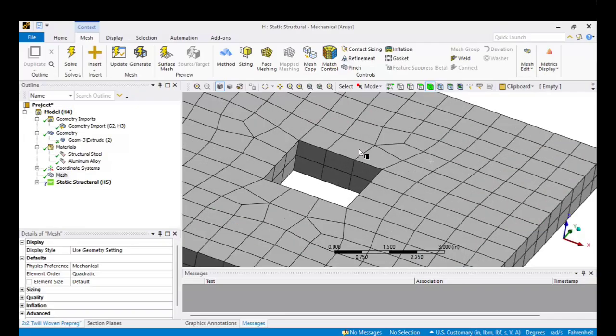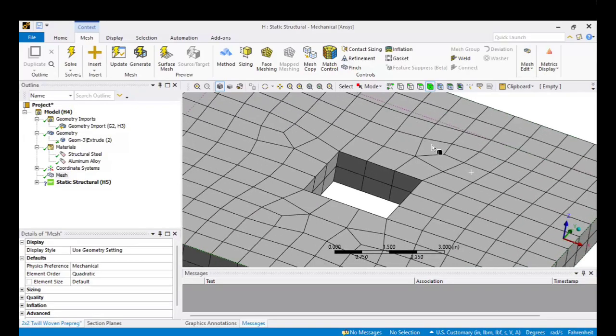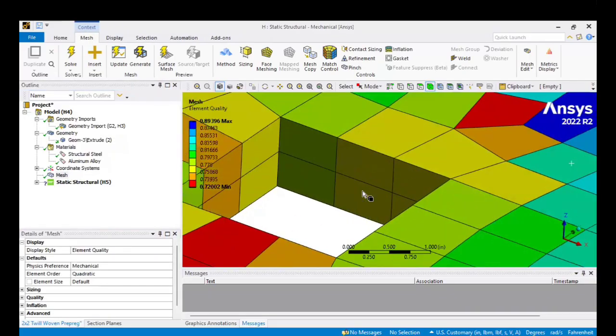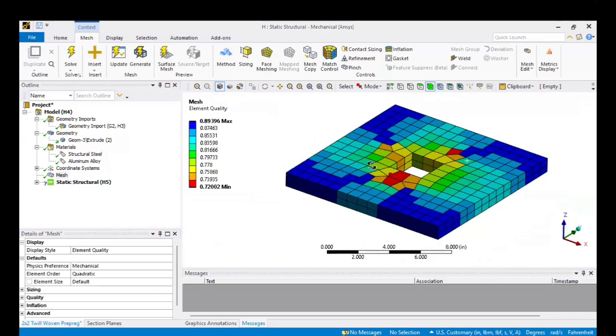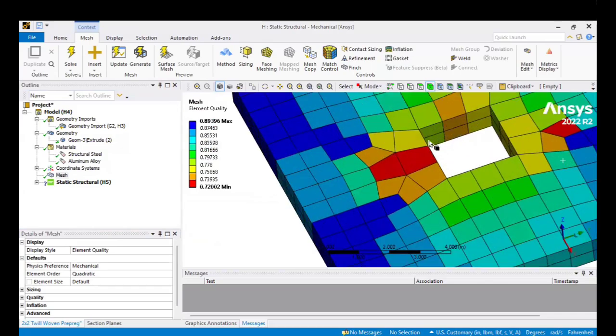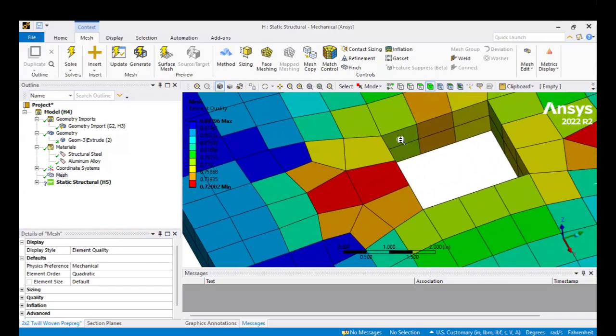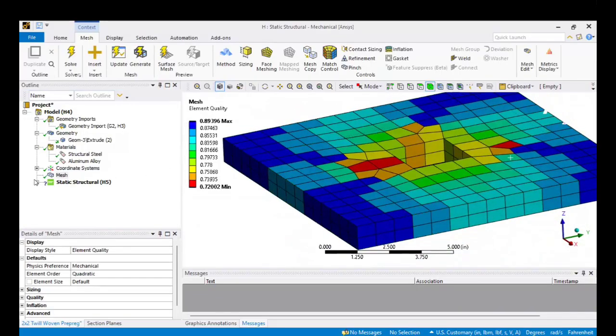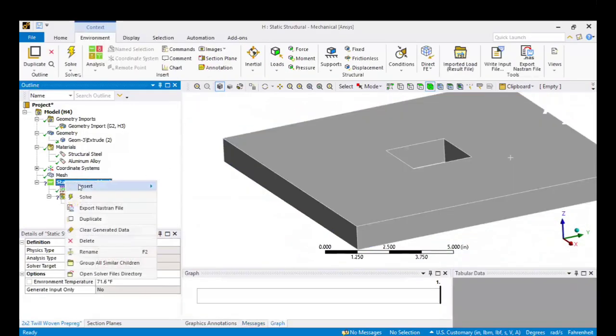It's created from your first project, and you'll know that meshes with very non-uniform shapes generally produce worse results. A way to look at this is if you change the display style to element quality, sometimes you have to refresh, you can see a good graphical representation of mesh quality. So first let's just load it like this and see what we get. Then we can change the mesh and see how that updates the stress concentration.